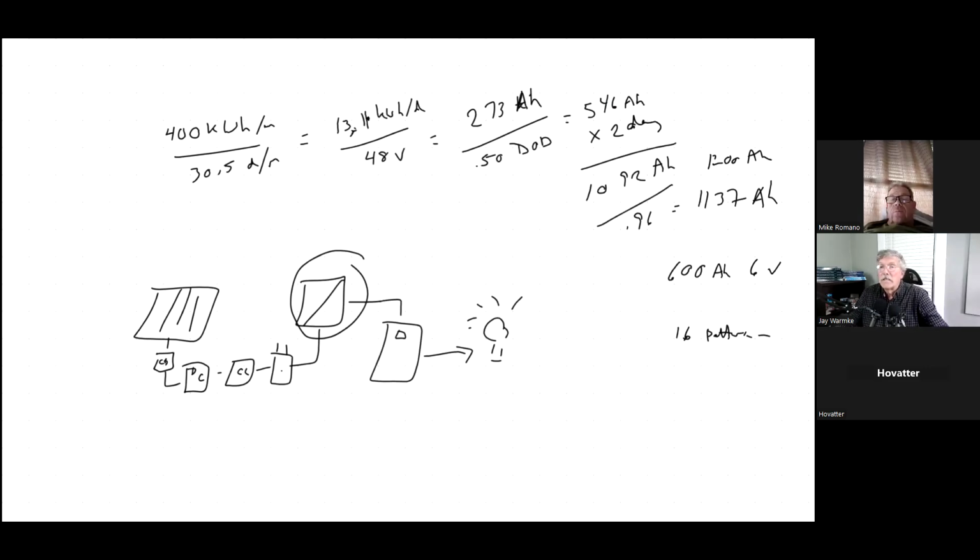So I go out and I price the system. If I want 1 day of autonomy, I would buy a 13 kW lithium-ion battery. That's it. All the derating, all the depth of discharge, all of that's already factored in. So very easy to size for lithium-ion. I would go out and buy myself a Tesla Powerwall that's rated at 13 kW. 1 if I need 1 day, 2 if I need 2 days of autonomy. That would be kind of it.